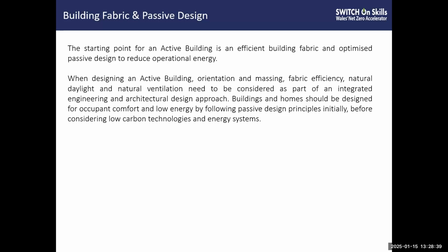The buildings or homes should be designed for occupant comfort as well as low energy by following passive design principles, and then also considering low carbon technologies and energy systems where possible. Things like building massing, you may or may not have heard of that before, but this refers to the overall configuration of the building. Things like site size, geometry, topography, and configuration in relation to adjacent streets or buildings and things like that, okay?